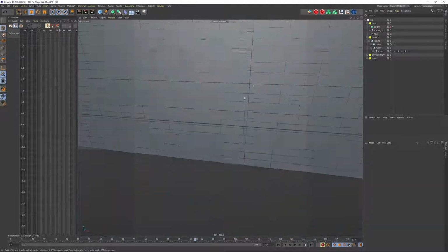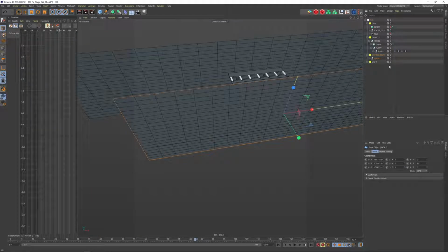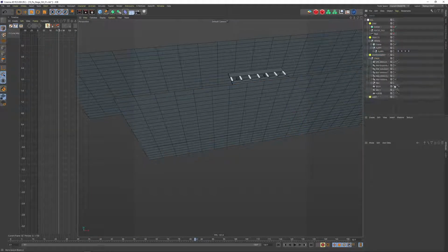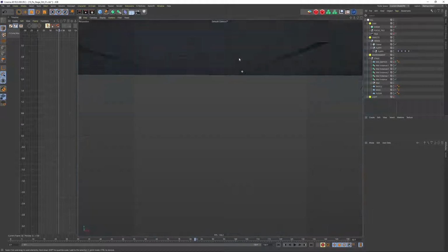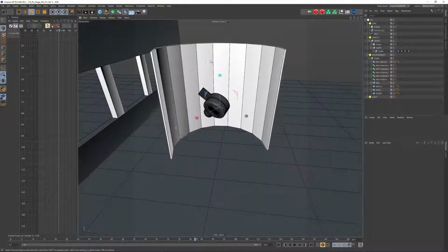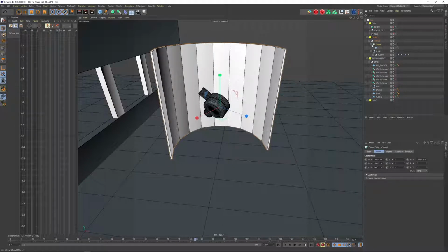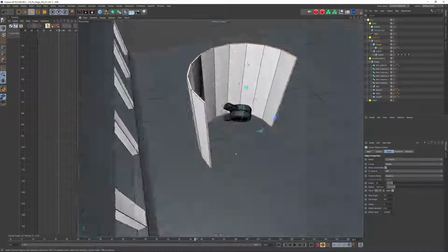So let's have a quick look at our scene, what happened. Let's first of all start to remove a few things so I can go through everything step by step, and we'll keep the floor for now. So let's get rid of all the walls here. Let's see what we got there. First of all, I created this element. It's a cloner with a cube, and in a cloner you can go to radial, and it has a radius from 130 to 132, but whatever fits for you.